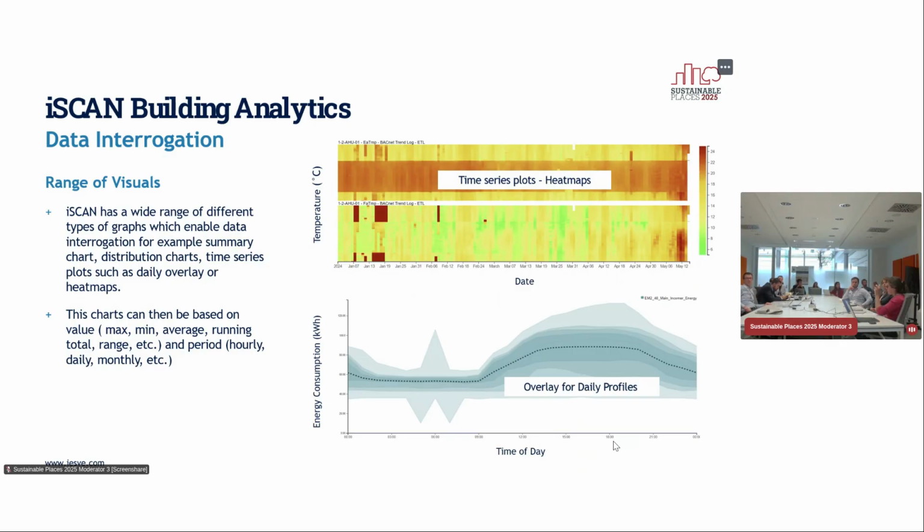This is a main electricity consumption graph, and basically we're looking at the average energy consumption by selecting, for example, a week, a month, weekends, or weekdays, and so on. It automatically calculates the average of that period. So it's very useful when auditing energy consumption to detect patterns, spikes, or something that's throwing off the building performance.